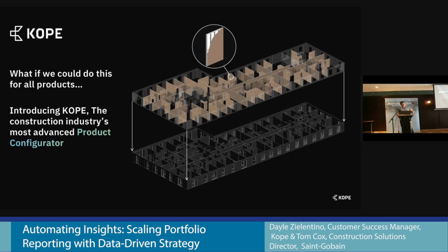So moving away from just the world of BIM, which is a data-rich object, but actually the adjacencies from one object to another, understanding that relationship and knowing the limitations on site. How heavy can a panel be before this just becomes unliftable? You can have a board or a panel that is of a certain size, but we are selling 120 kilos. That just isn't manufacturable by 2 people on site. Actually, you need to constrain it and understand the wider inputs and values that come into that.